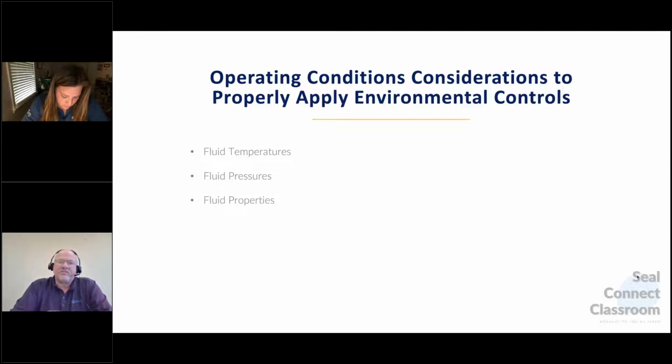What's happening is the water goes to steam, and you get these little explosions between the faces, and it chips the faces away. So the most common thing that's sealed in industry is hot water. You have to take special consideration when you seal hot water, with heat exchangers and different things that you do to help cool that water down, because hot water is a poor lubricant.